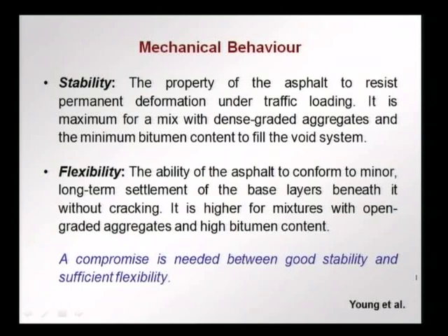This stability is maximum when you have an asphalt concrete mix with dense graded aggregates. Remember, we had talked about grading in the previous half of this lecture. Dense grading means there is very little voids, the aggregates are in contact with each other and load is transferred through the aggregate skeleton. The bitumen content is also minimum and there is basically an interlock between the aggregates. The voids, however, are filled with bitumen. In this case, we will have good stability in the asphalt concrete.